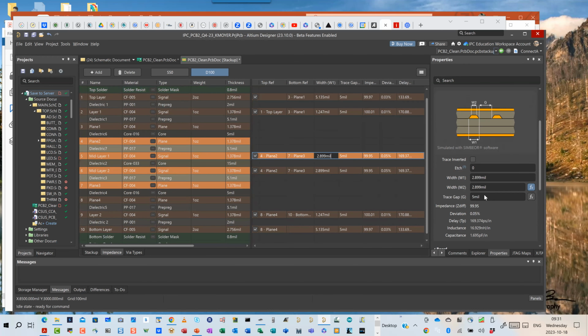And what we're going to do is increase this gap width right here. So instead of having a gap of only 5 mils, that was our minimum, I might make that something like 15 mils, and see where that gets me. And 15 gets me over. So you're basically going to turn the dial on gap width right here and see that, yep, that is going to achieve my minimum 5 mil gap and my minimum 5 mil width. So I've got my gap and width, my trace and space are both 5 mils or greater. So I'm okay making this out of my 1 ounce copper.